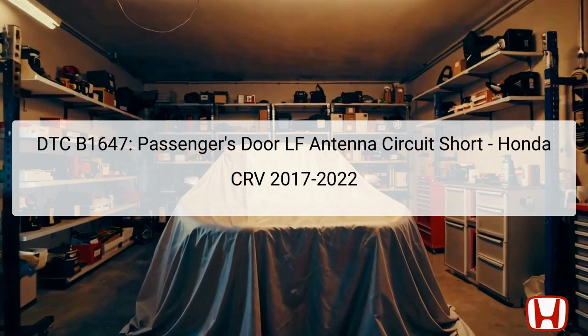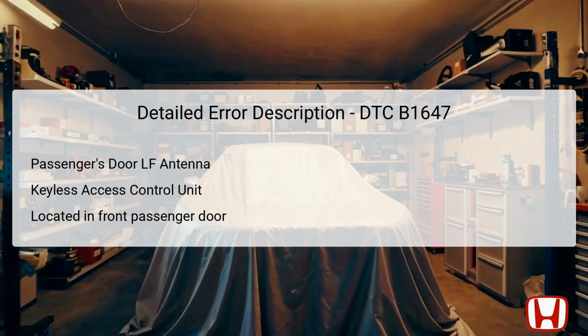In the Honda CRV from model years 2017 to 2022, the keyless access control unit plays a critical role in allowing the vehicle to detect the presence of the key fob and facilitate functions such as unlocking the doors without manual input. The front passenger door's outer handle contains components tied to this system. Troubleshooting this DTC is essential to ensure the proper operation of the vehicle's entry systems and to prevent failure of the keyless functions. The DTC B1647 specifically pertains to the passenger's door LF antenna circuit.